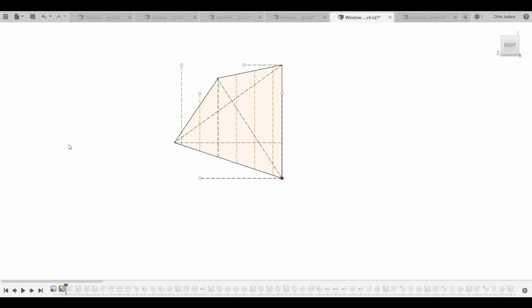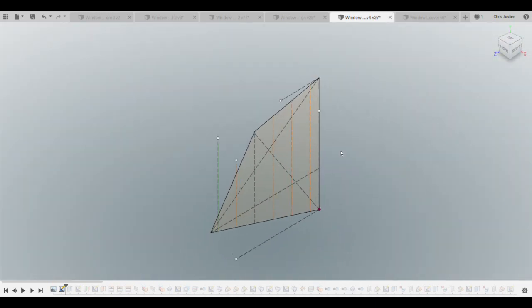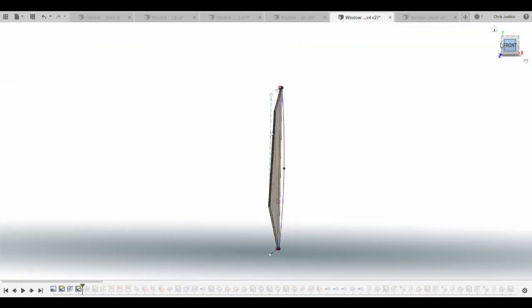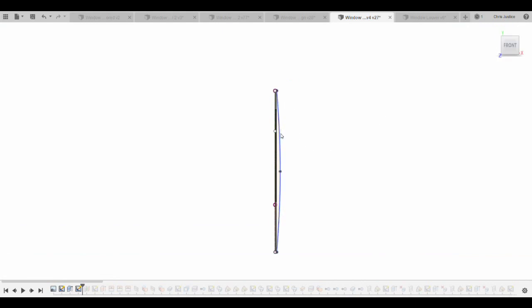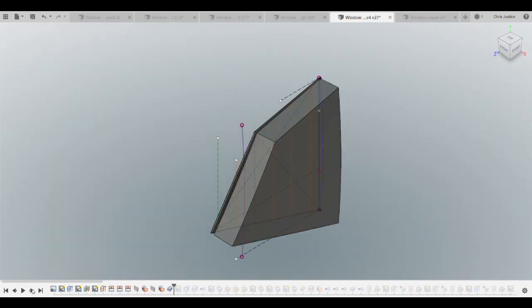After I had the picture of my taped window, I was ready to begin the 3D solid model of my louver. Keep in mind that I also accounted for the curvature of the window, as you will see depicted in the early modeling process. The first thing I did was import my picture with a 1:1 scale into the Fusion 360 software. From there, I created an outline from the picture. I then created a surface from the outline and added a sketch perpendicular to the plane that represented the window curvature. I extruded the surface using the curve as a guide, and I made sure to add extra material for the fin cuts.